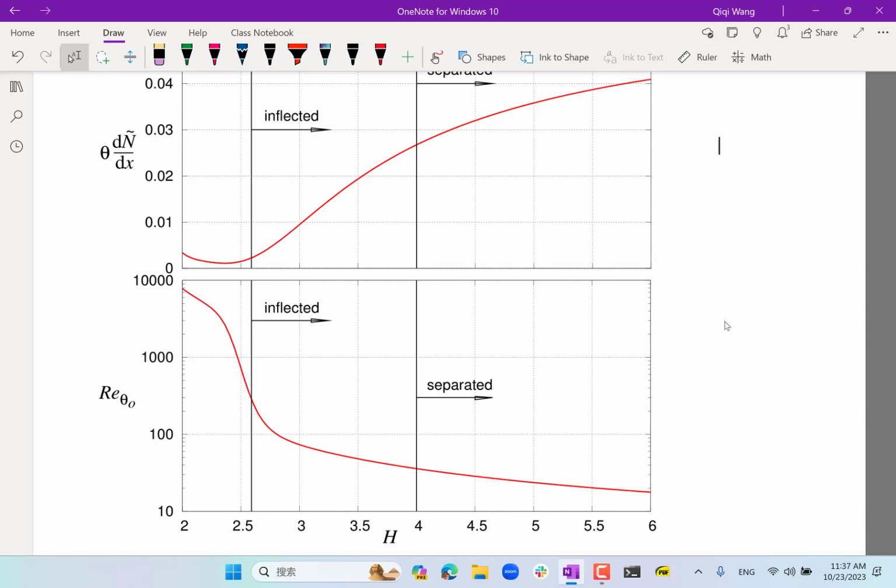And these tiny perturbations, for certain types of boundary layer profiles and thicknesses, are unstable, which means as these perturbations advance downstream, they are going to become larger and larger. And flow transition occurs when these perturbations become as large in magnitude as the steady state velocities in the boundary layer itself.